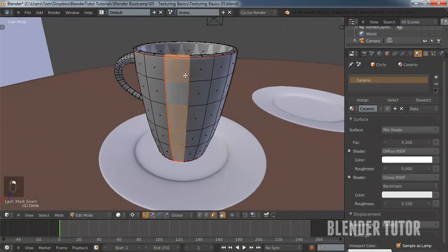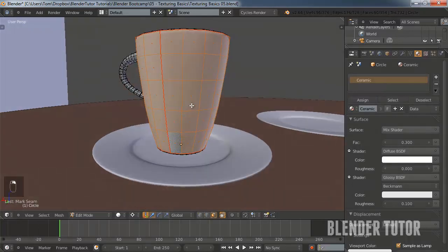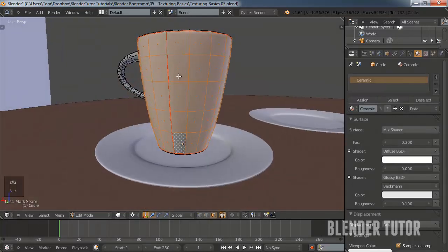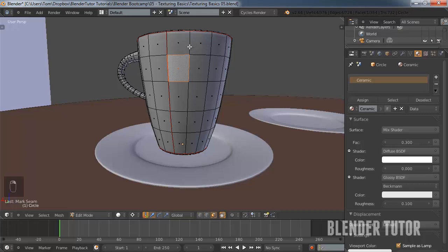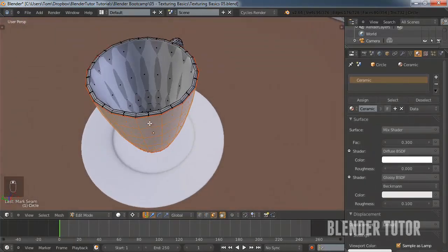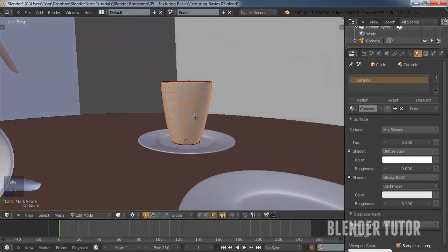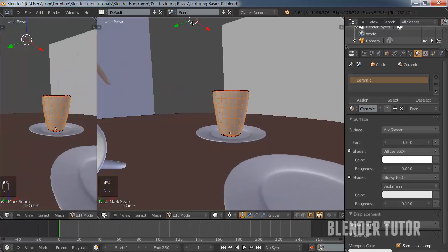Okay, so first what I'll do is select all of those. I got into this face mode by hitting Control Tab, and it will bring up this little mesh select. So I just select my faces. Now if I hit Alt, and then if I hold down Shift while hitting Alt, I could add all of these in one selection. Now the next thing we're going to do is basically unwrap the model so that this lays out flat. How I'm going to do that is I'm going to create a new window right here.